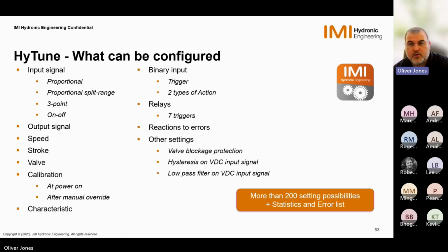We can also have binary inputs. So if you've got something like a binary input-output Slider 160, we can actually feed from the BMS a binary input, say from an actuator on a window. So the window opens, it sends a signal, and that signal gets pushed to the slider that tells it to close because the window's open. So the room no longer requires heat, and it will shut the heating off, or however the application is.